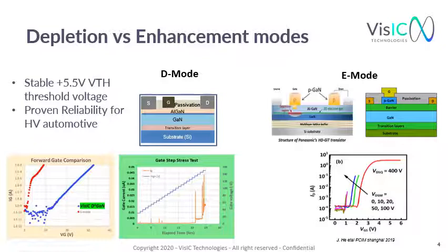You can observe that in voltage gate stress tests, D-mode gallium nitride devices can survive at much higher gate voltage stresses. The operation of the D-mode gallium nitride is generally from negative values, such as minus 15 volts in off state, to on state at 0 volts. In both positive and negative gate voltages, D-mode exhibits much larger voltage margins.